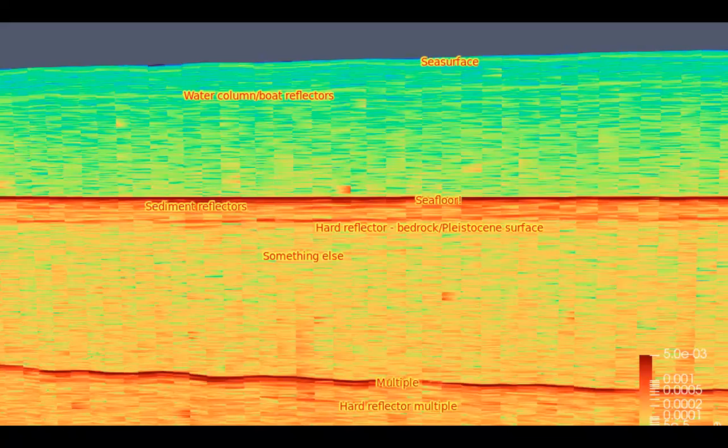Now, we'd basically see it at twice the depth of the seafloor because it's traversed the water column 4 times effectively, twice times 2. And we would actually exaggerate those seafloor features a little bit. So whereas our initial seafloor looks flatter, when it's traversed down, up, and then down, up again, it exaggerates some of the structure in it. So if you actually see something like this, it's almost exactly twice where the seafloor is, and the structure looks the same, maybe a little exaggerated. And if you actually look underneath it, I can see this hard reflector I've labeled underneath the seafloor, repeated as another hard reflector underneath. We're actually repeating structures within that upper reflection profile as well. So this is all artificial.